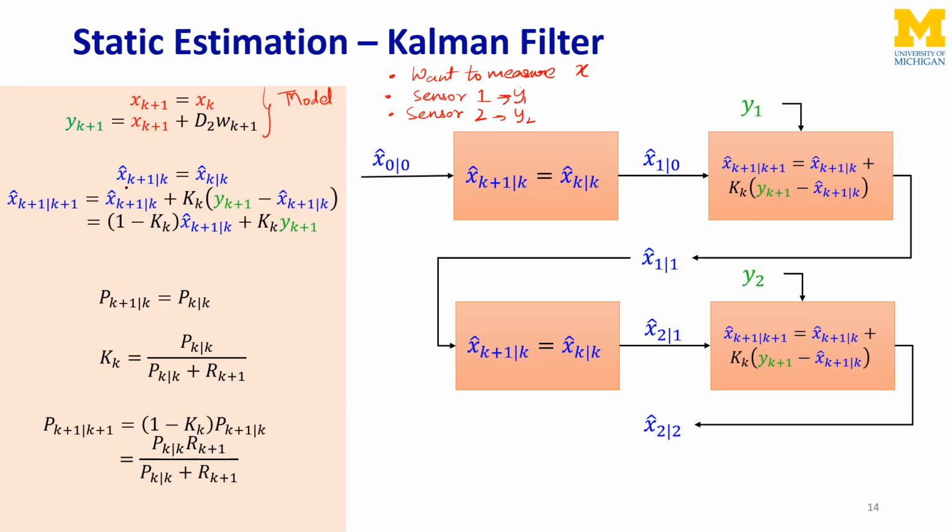We have the Kalman filter, and in this case it can be written as this equation, and you see what's happening here. The estimate at step k plus 1 is, again, a convex sum of the prior estimate and the measurement. And the gain K is given by, of course, the Kalman filter. For the scalar case, where A is equal to 1 and C equals 1, the P_k, the K_k, and the posterior covariance matrix are computed by these three equations.